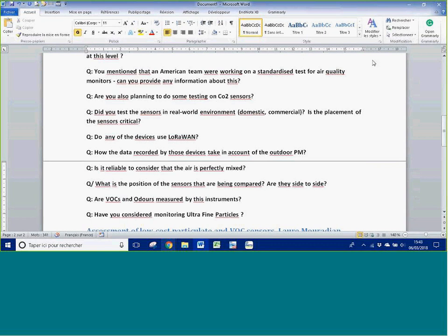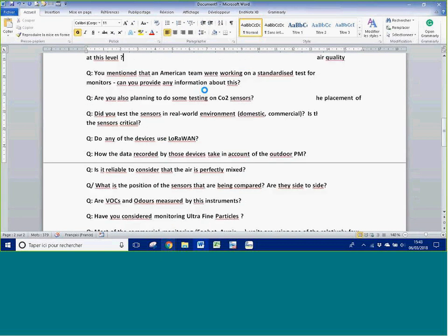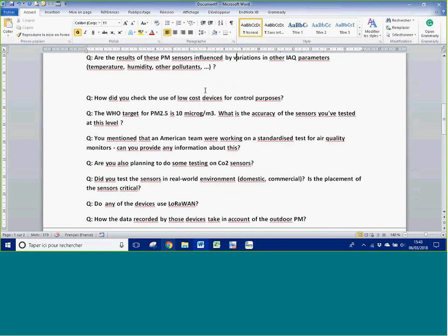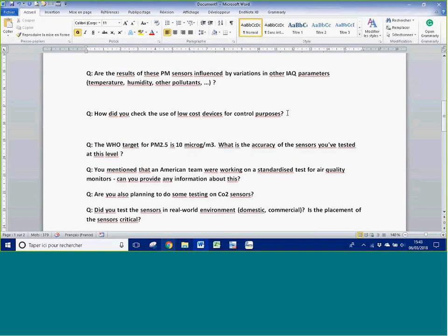The reason for that is most standalone devices that are used for particle filtration, I'm talking about devices for a home here, not something built into, say, the heating, ventilating, and air conditioning system of a building, but a standalone device you can put in a room that has a good particle filter in it. They have basically the same sensor also. It's just hardwired to a fan control right inside the box itself. And we have done field studies of those standalone devices where they have their own sensor built in, and they work very well for particle control. They can be good at detecting particles, turning on at the right time, turning off when particle concentrations are low, and generally they do a very good job of keeping particle concentrations low in a room.